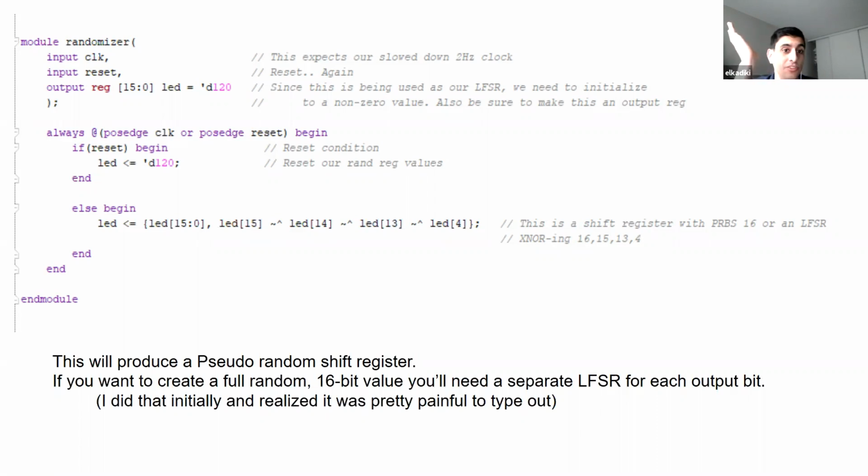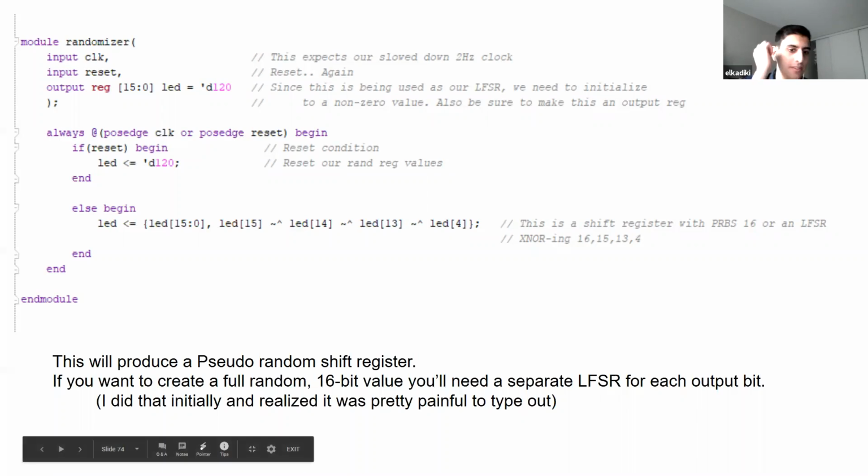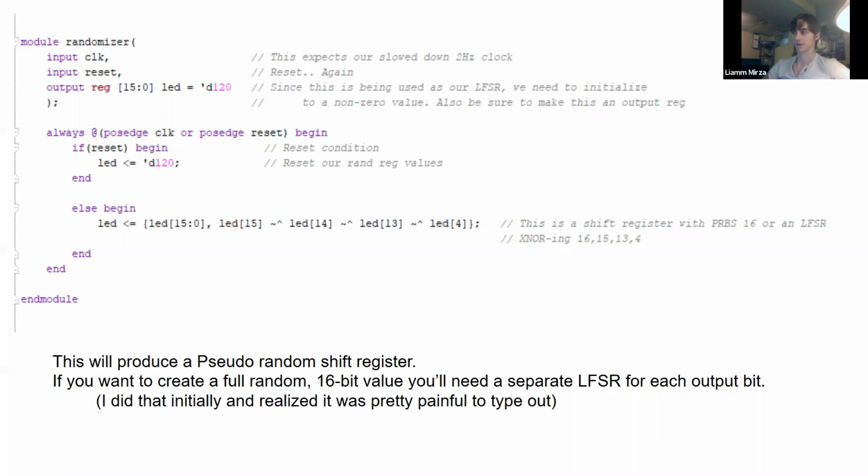Pick your favorite value between those values, maybe the last 2 digits of your student number or something like that. That's a decimal value. We want it to be between 2 and 127. Notice the D in front of the numbers. That's very important for telling Vivado what kind of number you're using, because you can also do this in hexadecimal or octal format.